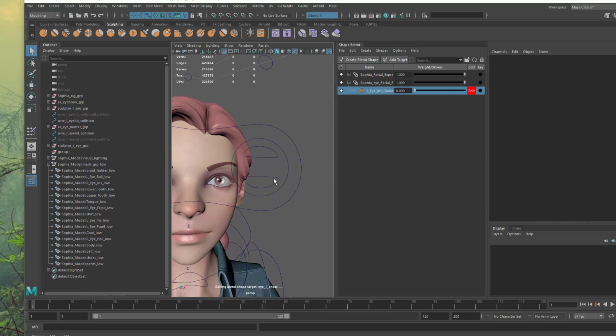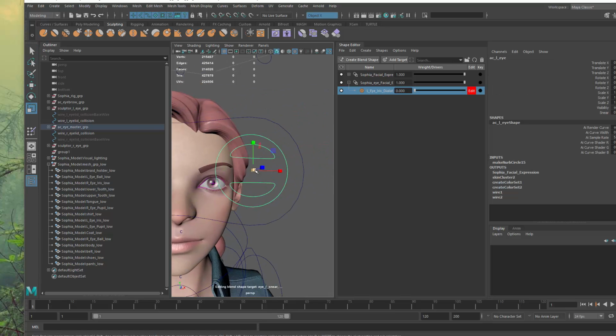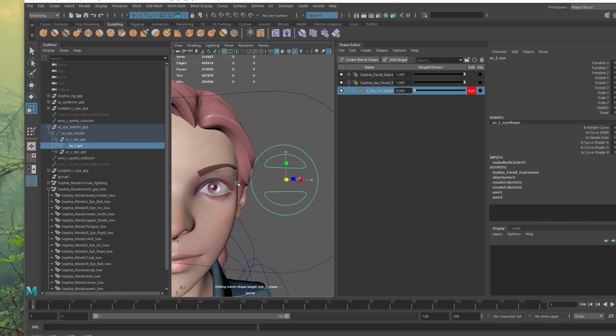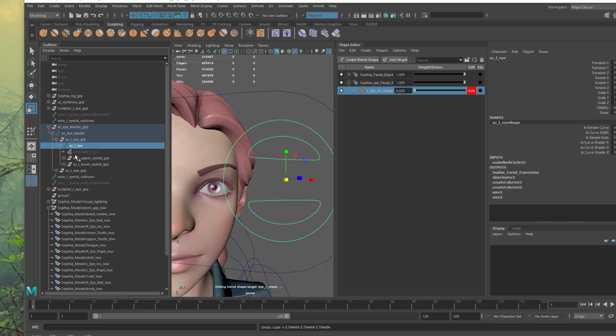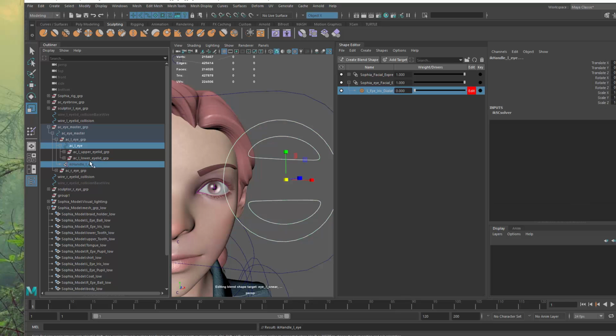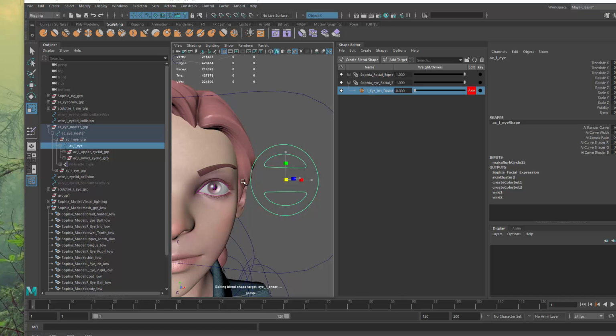and that's going to be actually the scale of my eye directional control. But when I scale it, you see the joint is rotating a little bit. That's because of the IK handle right underneath it. So what I'm going to do is parent the IK handle to the group instead of the controller, and grab the controller and the IK handle, and do a rigging constraint and then point. That way the scale will not affect it at all, but the movement still works.